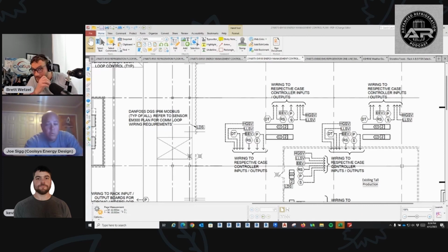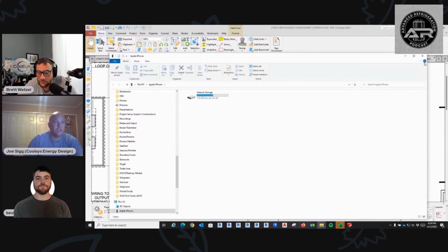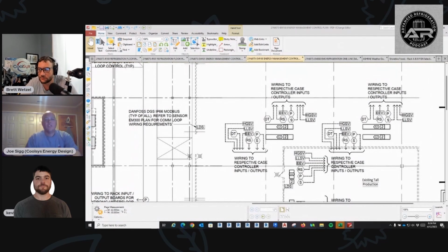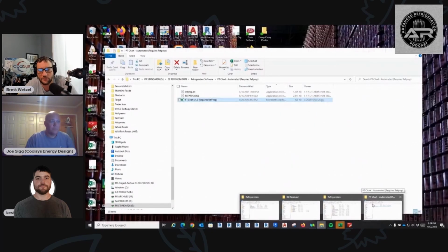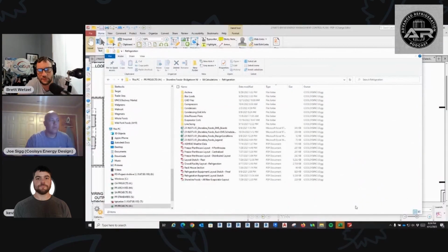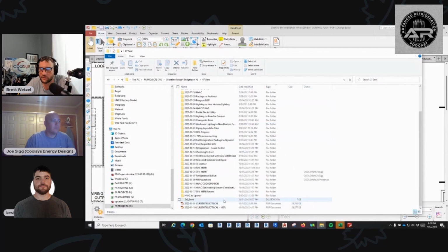Go ahead, sorry. So the only time that we put bypass check valves around devices in our CO2 refrigeration systems is when they can positively shut, like a solenoid valve, like a hand valve, that kind of stuff. But EPR will close. Yeah, Brett. So the way they have to do that, because I just had to do this at the store, you have to check it to the liquid line.